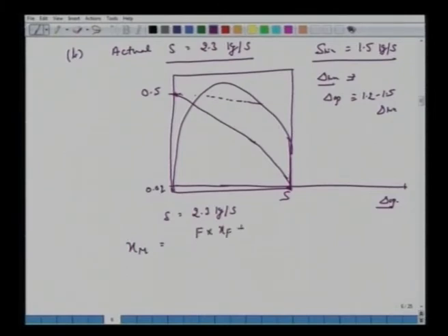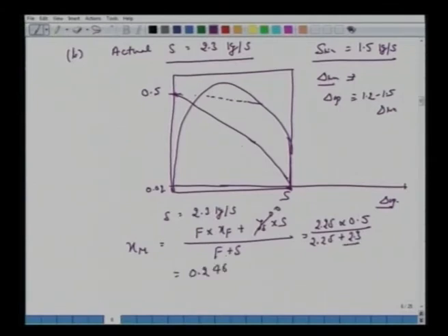So now we have XM slightly lower here. Now what is the idea of this XM? Once we connect with this 0.02 to X1, now we have E1 right here. Notice this corresponds to E1 min. Now we have the extract concentration which is smaller. Why? Because we have taken a larger amount of the solvent. So it is a multi-stage, feed getting in here, raffinate getting out here. We have the solvent getting in here and we have E1 leaving from this stage 1. So when we take the larger amount of S, the concentration of solute in the extract phase is smaller.